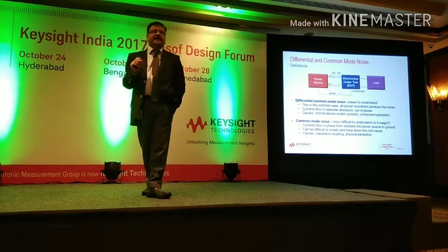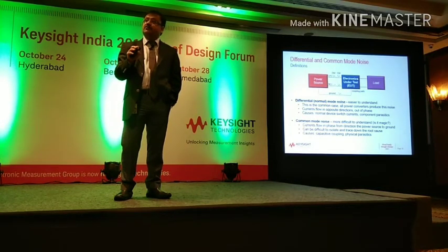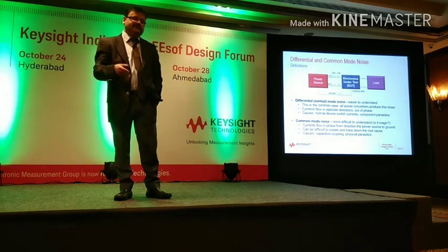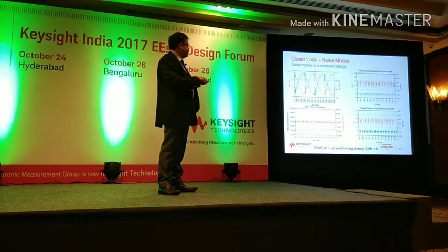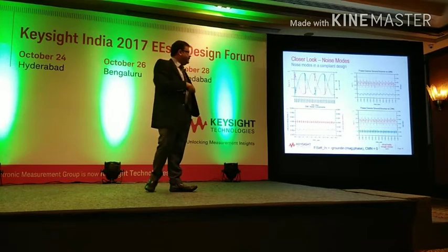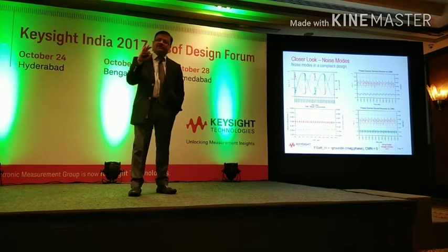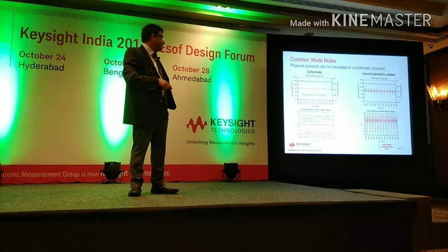Physical parasitics can arise either from the components which you have used in your circuit, or due to the layout which you have done, which is giving rise to those parasitics. Okay. So I'll just skip some of these. If you take a closer look at the noise modes in a compliant design, the red one is the common mode noise, and the blue one is differential mode noise. You cannot have zero noise for sure, but as long as your noise is below the threshold, which is not causing an EMI issue, that's okay. So you need to just contain the noise below a certain threshold level.